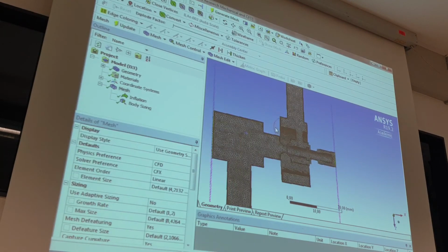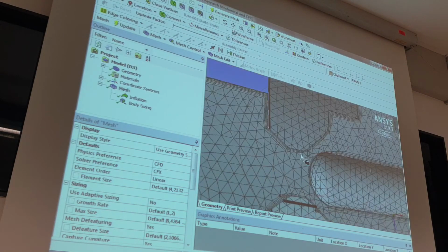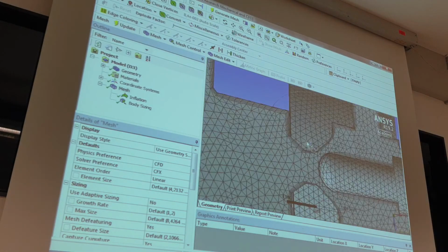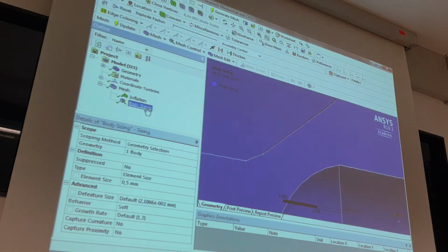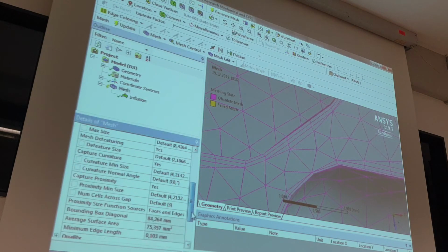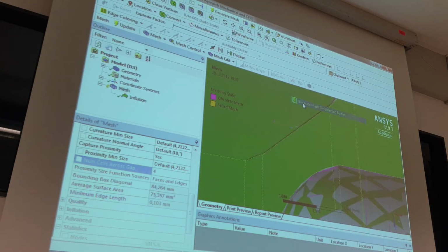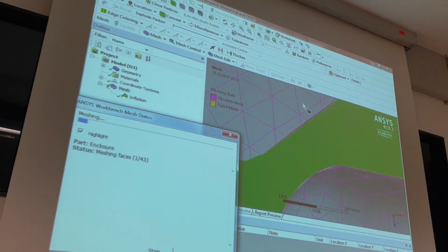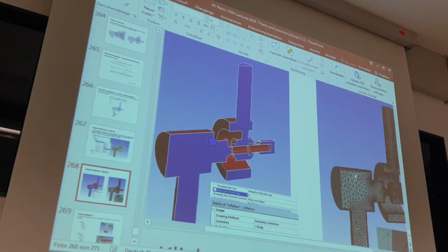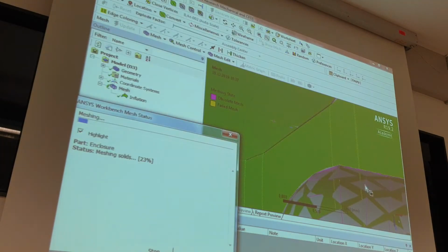So look, now it's bad. Yes, also bad. Look, now we have fine meshing, but in the wrong places. And this is the question: what do we have to do? Maybe it was not so bad a solution with 4 elements across gap. It was fine from the inflation side. Yes? So then we try to do it like in lectures again. Okay, 200,000 elements, but okay. What can I do?